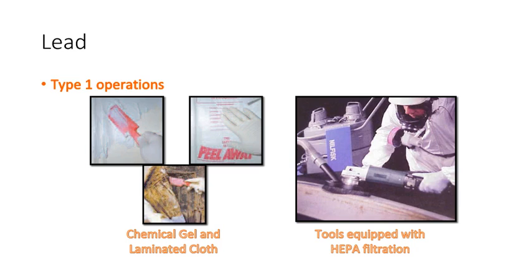Soldering. Effective implies that the dust collection system should be capable of controlling airborne lead concentration levels to below 0.05 milligrams per cubic meter. Employers should follow manufacturers' recommendations and maintenance specifications for optimal function of the dust collection system.